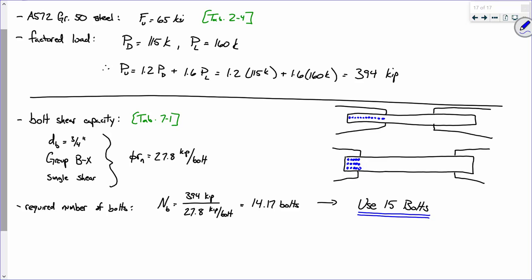For instance, there's an OSHA requirement that says if you're erecting a structure, there's a requirement called the 2-bolt rule. In other words, you're erecting a structure, so you got a crane that's picking up some large piece of steel, right? And say it's a beam going into this building. So the crane's lifting it here, and then the crane holds it there, keeping it levitated in place, okay? Then you got the iron workers installing bolts on either end. The crane won't let go until you got at least 2 bolts in on either side, okay? That's just basic, because what happens if it's installed improperly and one of those bolts snaps? Somebody on the ground's not having a good day, okay? You see what I mean?